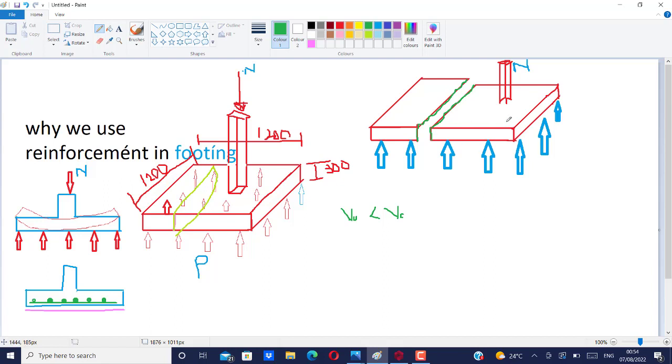As a designer, if the thickness of your base is getting more than 550, or probably 600, it becomes kind of ridiculous to choose a base thickness higher than this, because you might be requiring so much reinforcement to cater for the load that is coming.